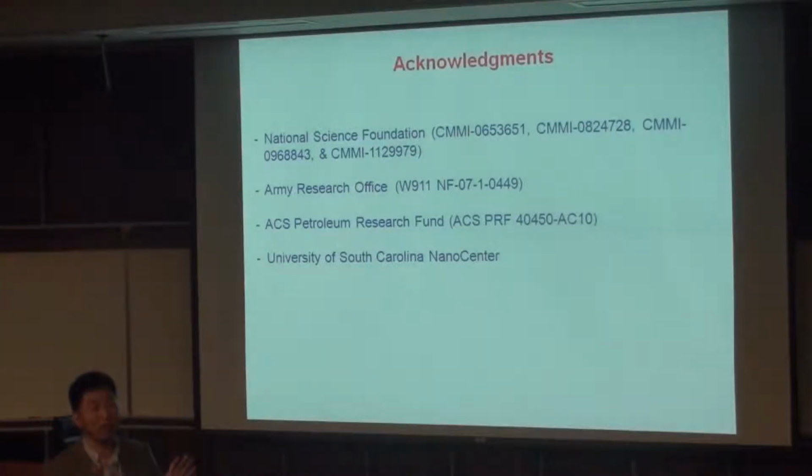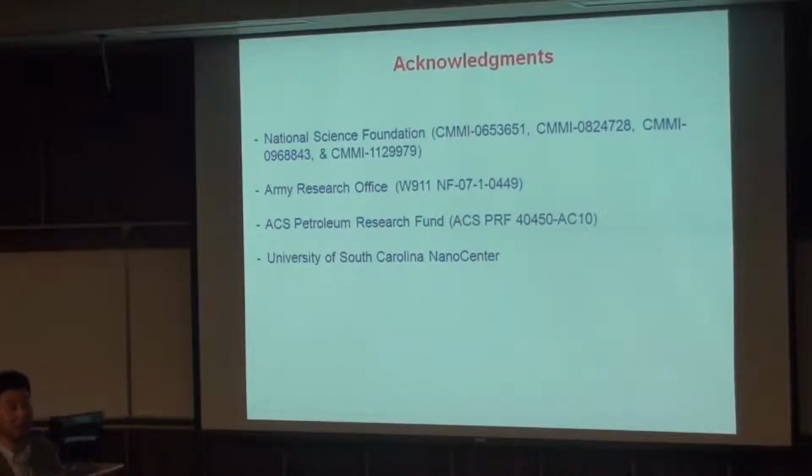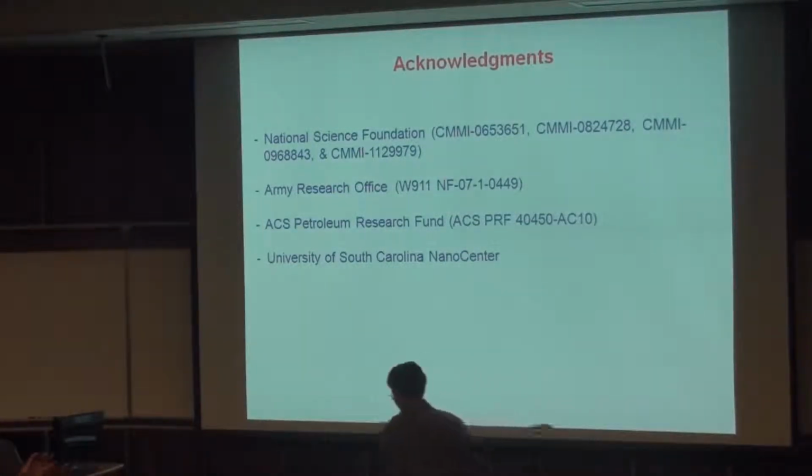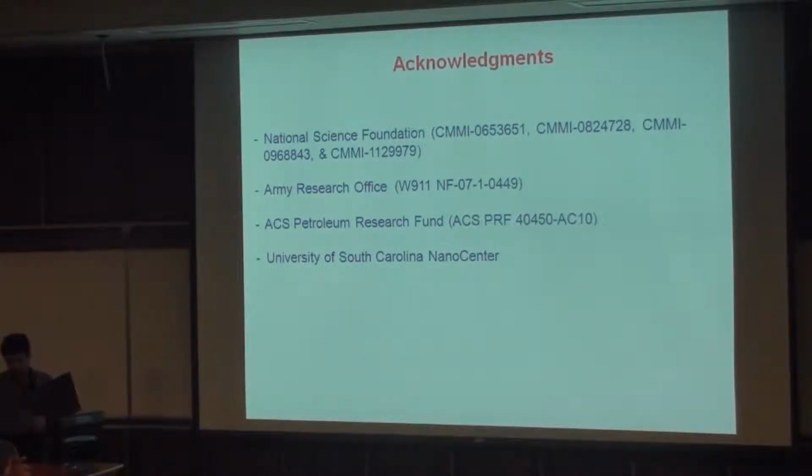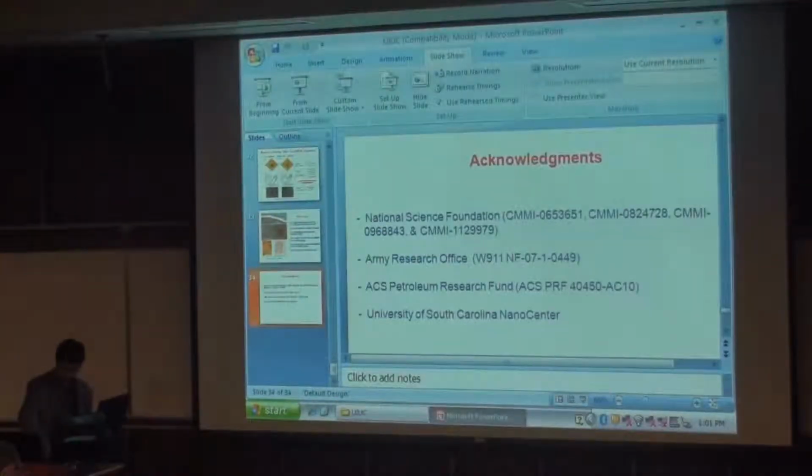Yeah. I try to borrow his stuff and your stuff. The thing is, Nacre's design is a hierarchical, multi-scale structure, and between those nanoparticles there are biopolymer layers. When you have stress concentration, this 3D network biopolymer can distribute the stress concentration far away from the crack tip.